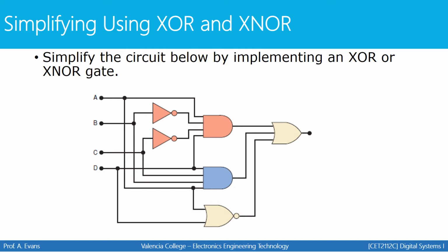And here's the solution to this particular circuit. We're going to start by writing the output expression for the circuit. I'm going to begin with the AND gate right here. Notice that A, not B, not C, and D go into the AND gate. So that's what's coming out of the AND gate: A and not B and not C and D. Notice with the blue AND gate here, we have D going in along with C, along with B, along with A. So now we have A and B and C and D coming out of this AND gate.